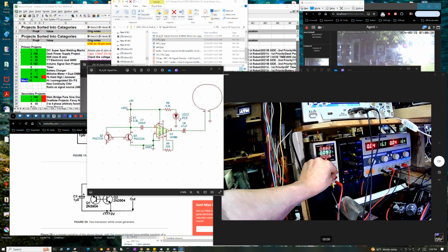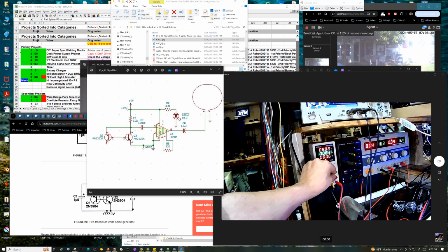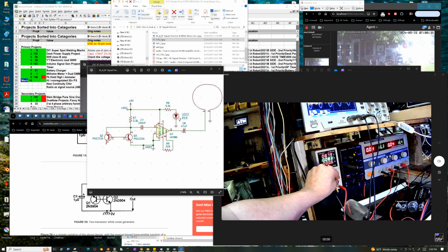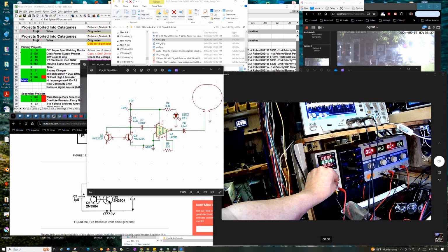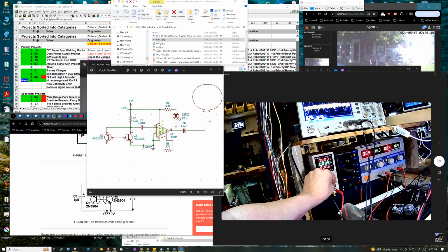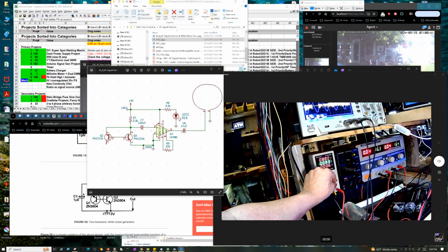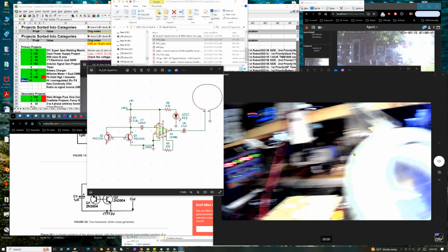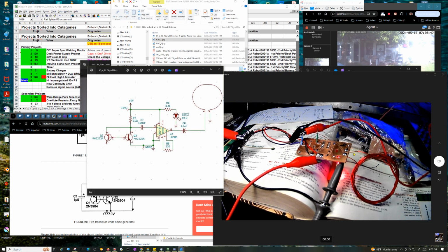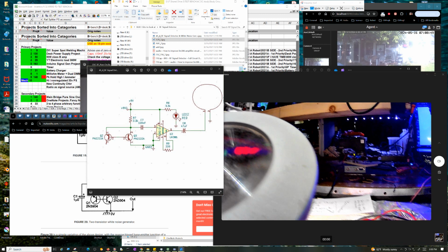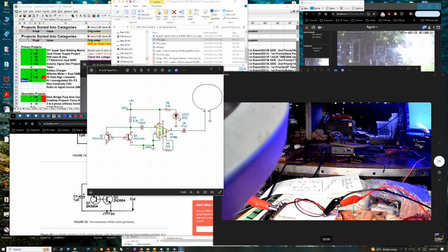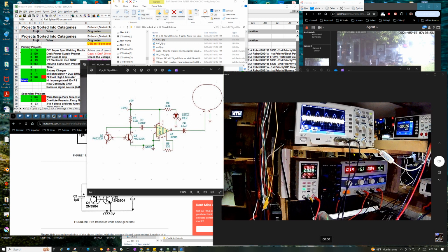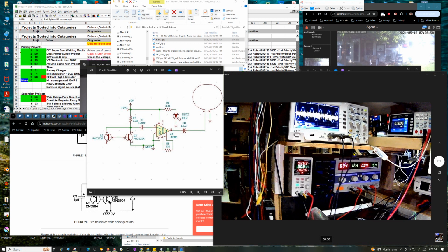That's not good, because you don't want to put even 1 amp of current into this thing, because it's only like a 700 milliwatt amplifier. You don't even want to put more than 100 milliamps into it. So that's why I'm trying to limit it. But this thing's got dodgy behavior. And even if I try to put like 30K of resistance in it, it just freaks out even worse.